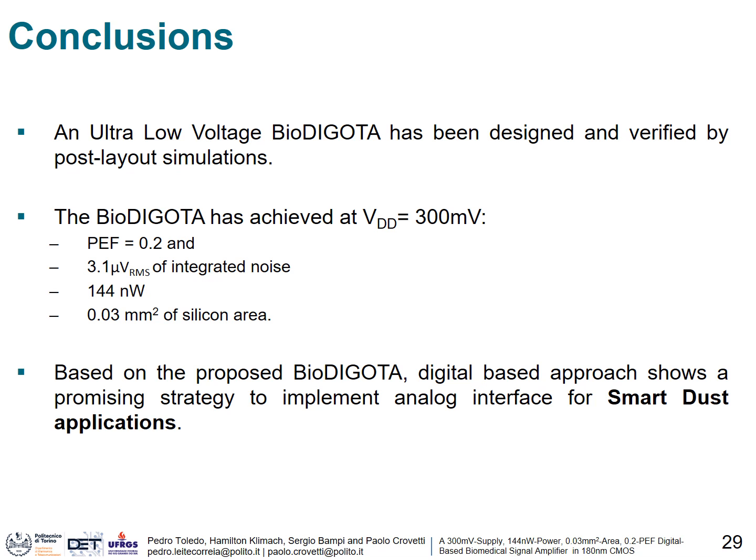It consumed only 144 nanowatts, and the total area was 0.03 mm². Based on the proposed BioDIGOTA, the digital-based approach shows a promising strategy to implement an analog interface for smart dust applications.